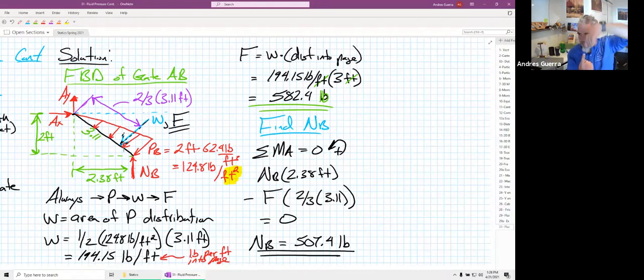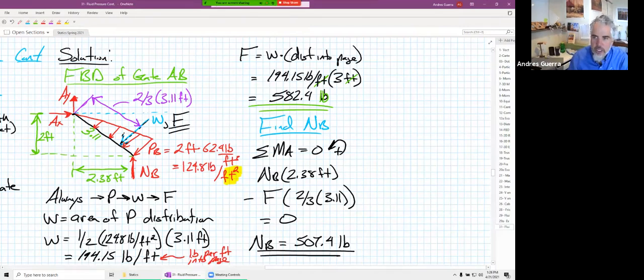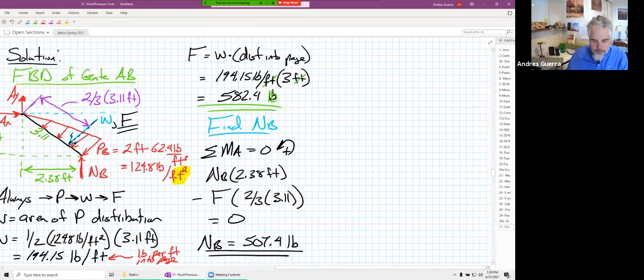So thinking about the stabilizing force by sloping our gate on the dam, look how big of a factor it can play. Instead of causing all this force, causing the concrete to shear off the top of the dam, by just changing our geometry, we're able to turn that force into a benefit during those large earthquakes. Any other questions?